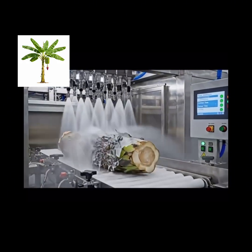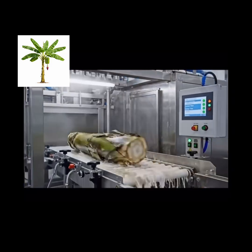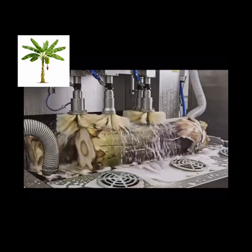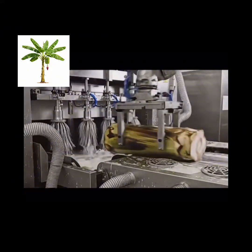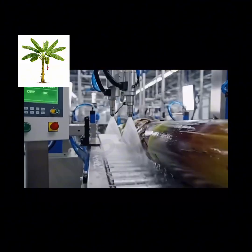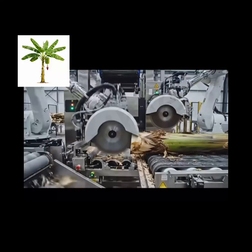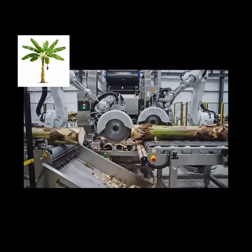What comes out of the decorticator is not yet clean fiber. It is a bundle of long fibers mixed with sap, pith, and plant residue. This material moves immediately into washing systems. In washing systems, fibers are sprayed or immersed in clean water to remove remaining organic matter. Industrial systems use controlled water flow and filtration so that the waste material is separated and the water can be recycled.